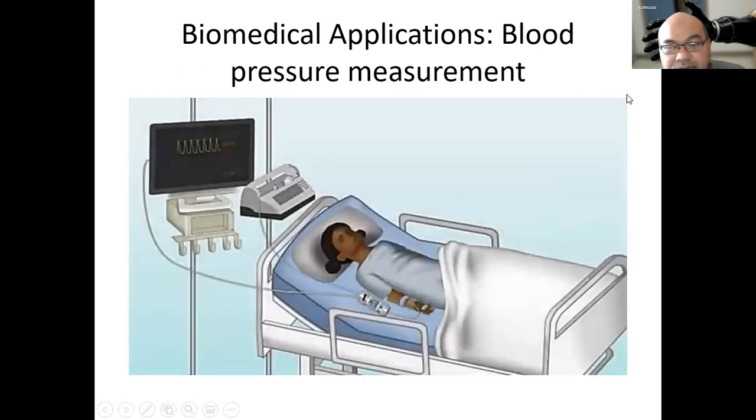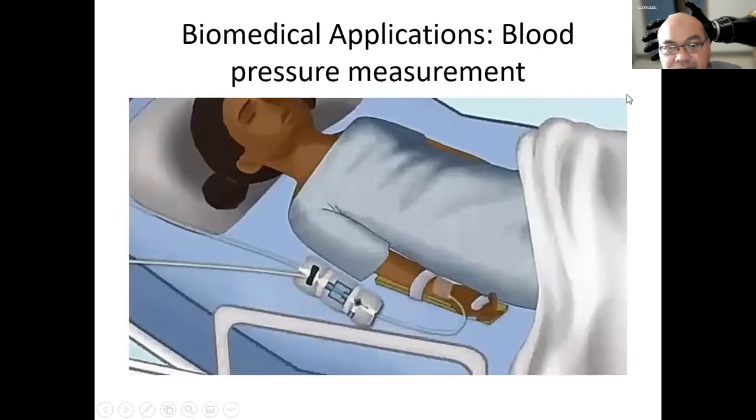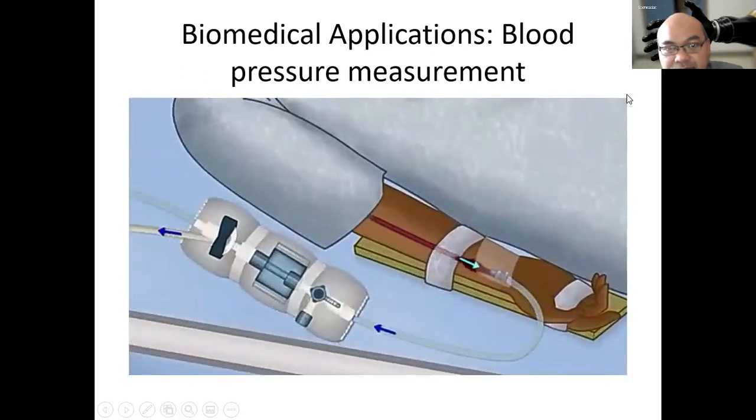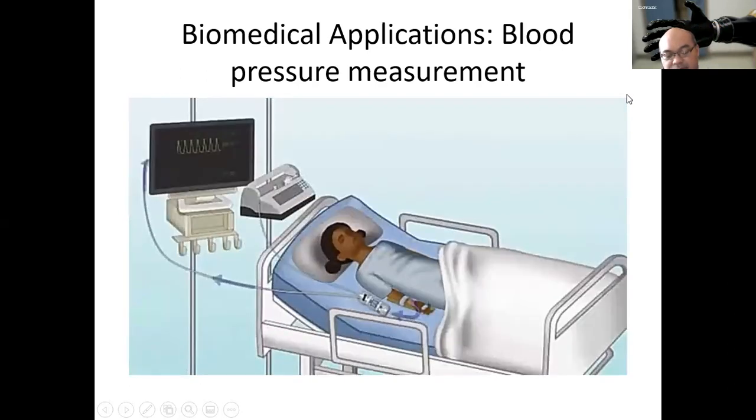Transducers are a system that converts a mechanical signal, which in the case of pressure monitoring, both for arterial lines and central venous pressure lines, is a pulsatile signal. It's converted through the transducer and then through this cable to a digital signal, a pressure waveform, which is what you see on the monitor.